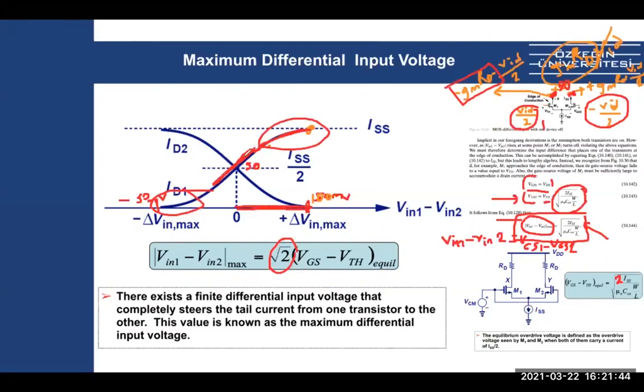The slope shows your gain. But now, as you can see, your slope is getting smaller. Your current amplification is getting smaller because now you are out of the range. So if you are out of the range, even here or here, now your circuit is kind of saturating, right? You don't really get to see the benefits of your circuit, okay? And we don't want this.